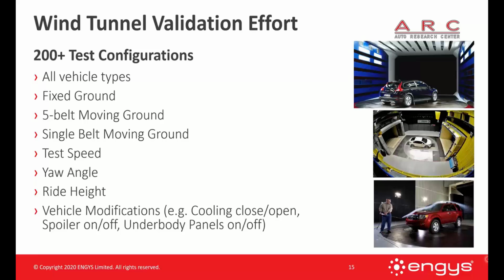So these different test configurations could be different configurations of the wind tunnel, or we're talking about different speeds, different yaw angles, different ride heights, different vehicle modifications. So open or closed cooling, spoilers on or off, underbody panels on or off, air dams on or off. So there's lots of different configurations for these different vehicle types in order to give us a better understanding of